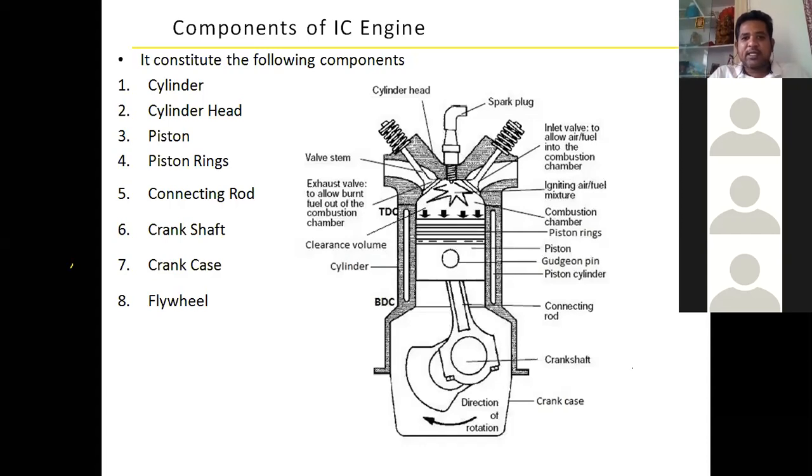So normally the cylinder head is going to be a separate component, as you can see here, just a small line. So this differs from the cylinder and the cylinder head. In this cylinder head, we mount the valves and the fuel injector or spark plug based on the application, right friends? These devices are not going to be an internal part of the engine, it's a separate part, because most of the time it is easy to maintain, and easy to remove as and when required.